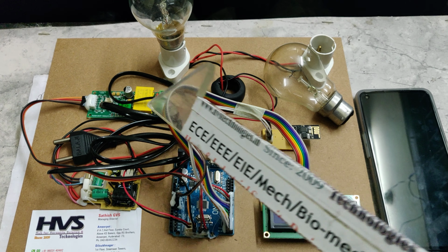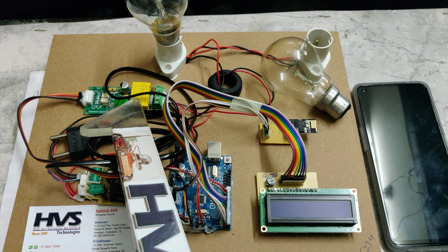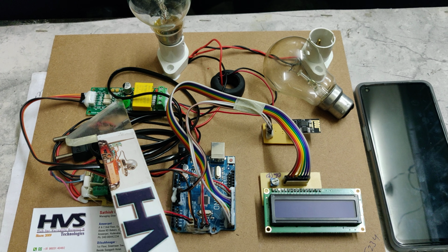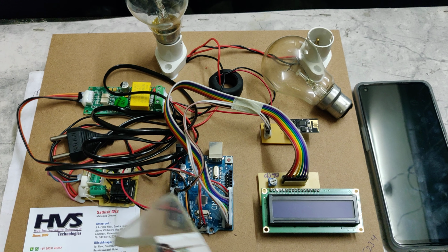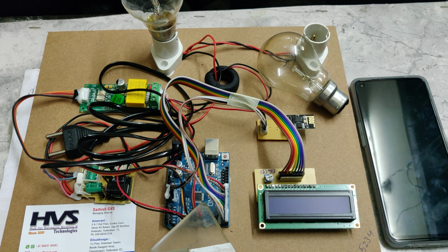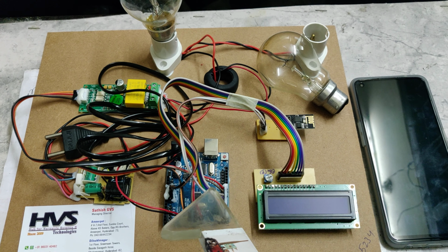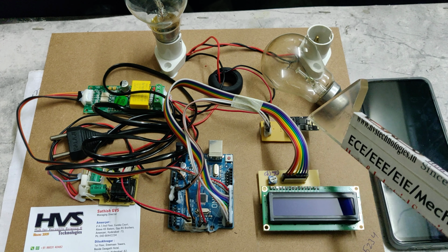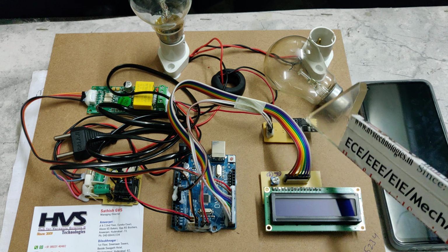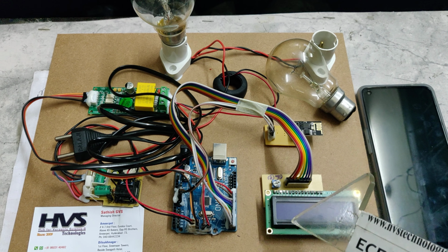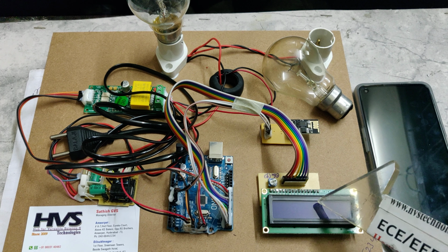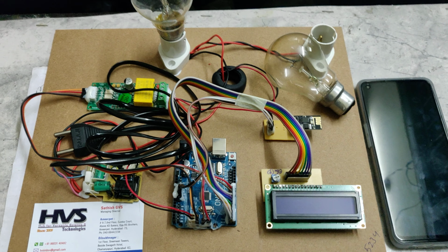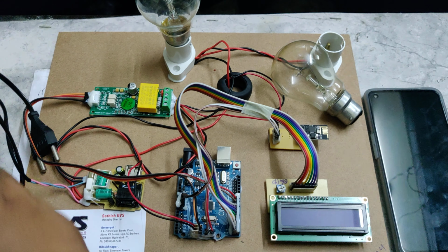Those 6 parameters are achieved with the help of this PZEM004T module, which provides us the TTL output. That was interfaced to our Arduino Uno board at pin numbers 8 and 9. The data is sent to the cloud through the ESP8266 module, which is interfaced to pins 0 and 1, and the 6 parameters are displayed on the LCD display continuously, which is interfaced to pin number 2 to pin number 7.